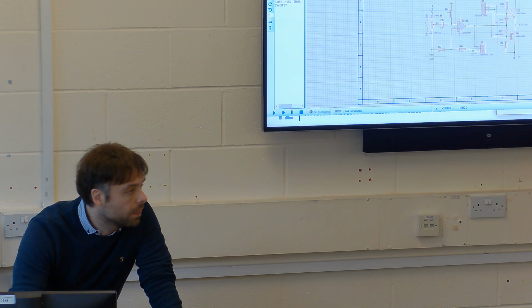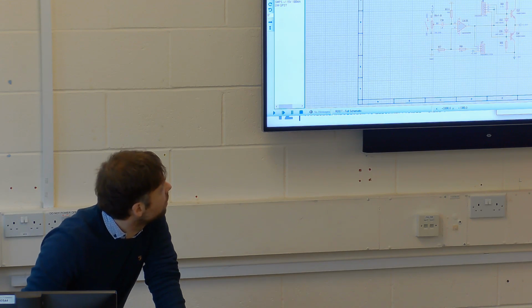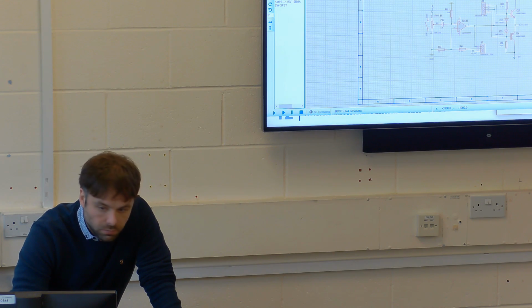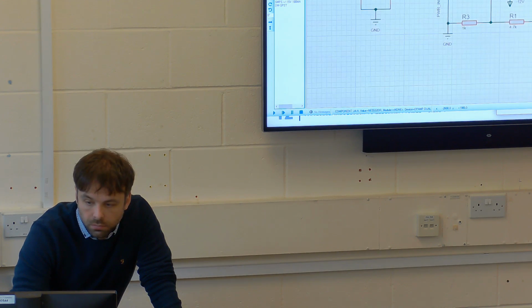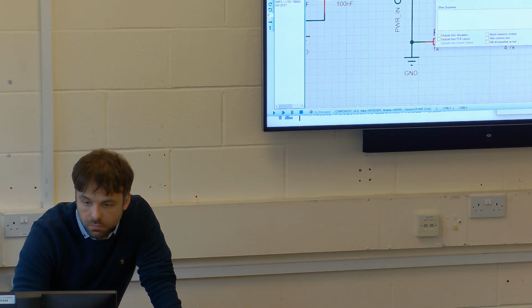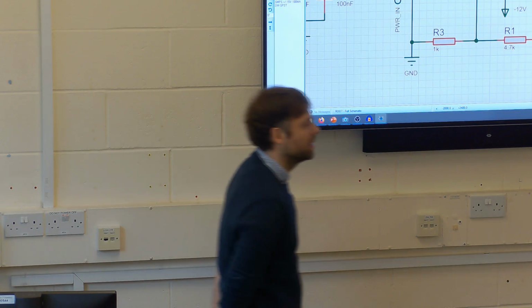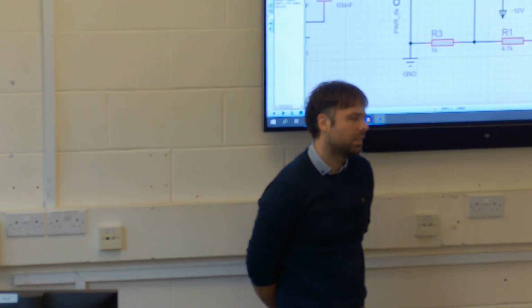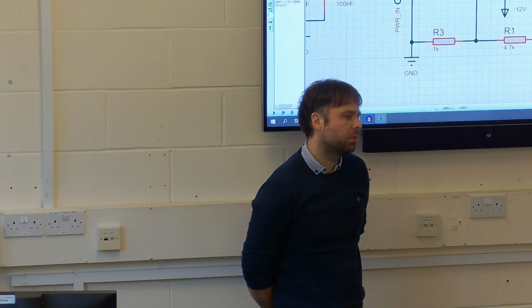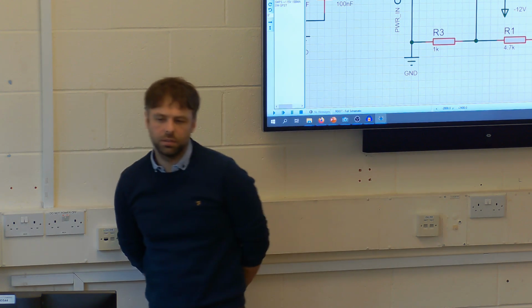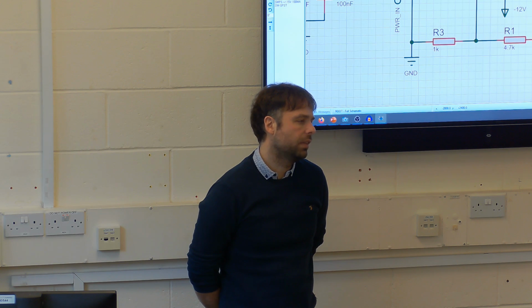Just to ask a question. Originally, you'd had NE5532APs. Seems you've changed it to DR. I missed that. Why did you change it? Did I? I can't remember. Does it matter, basically? I think the AP is the PDIP package, the through-hole larger device. So you went to a surface mount? I went to a surface mount one. Oh, okay, so we changed that as well. I don't even remember that I did that. If I did, I should have.